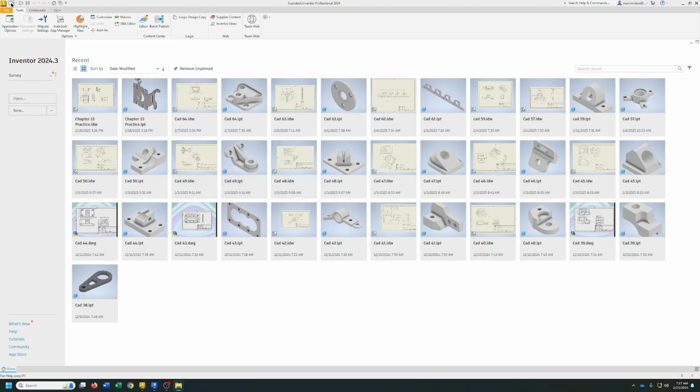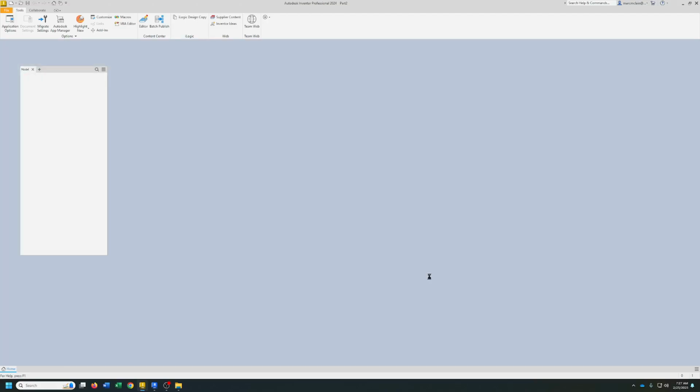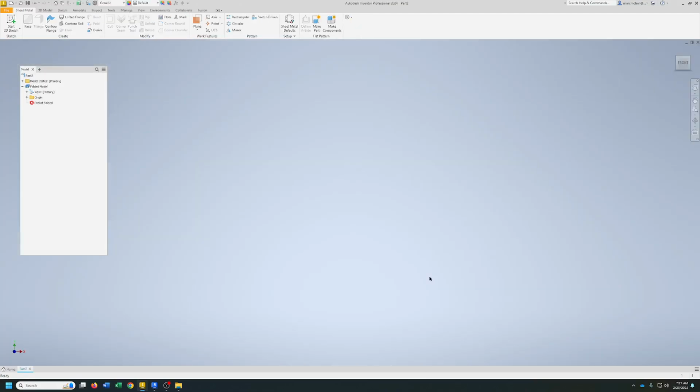And we're going to do this. It's going to be English, and it's going to be sheet metal. So we can click that and create. Now, look in our book, it gives us the coolant fan cover, and it gives us a list of 5 things. Number 16 gauge mild steel, standard straight relief, flat K factor of 0.44, bend radius is thickness, and all bend angles are 90 degrees.